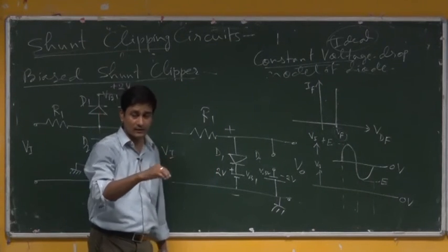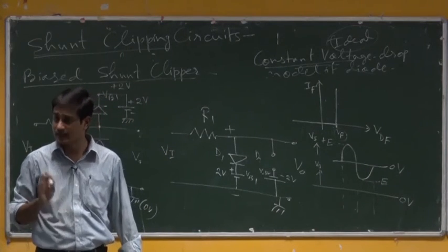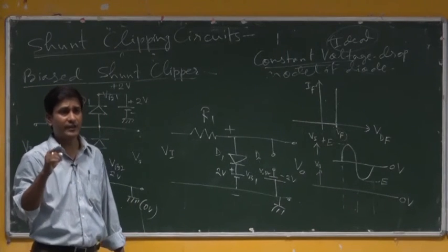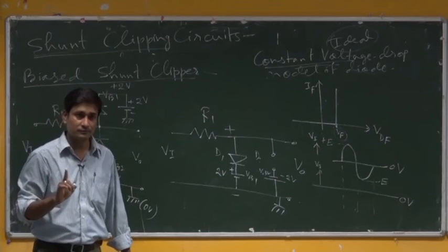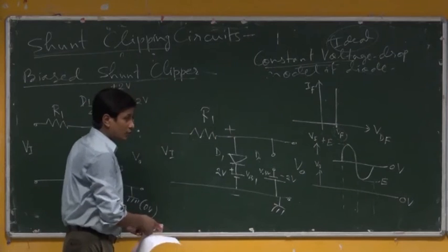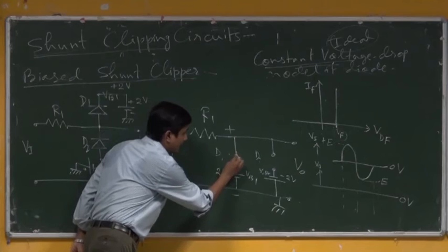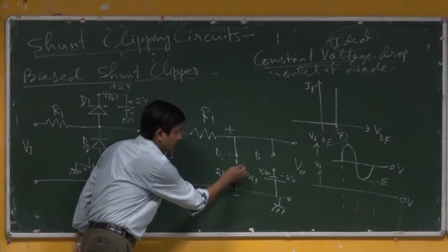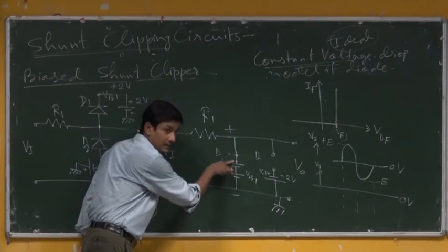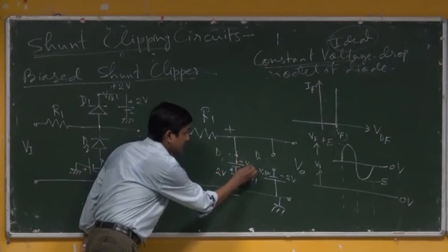Yes, in the last previous class, a few people were asking, is there any discontinuity? Yes, there is some discontinuity because of that VF. But the discontinuity can be removed if you consider VF equals 0. Okay. So if it goes beyond VF, you will equivalently represent this as one ideal diode which is short, and then what should be the potential? Plus here, minus here, because P was up and N side was down. Plus minus VF.